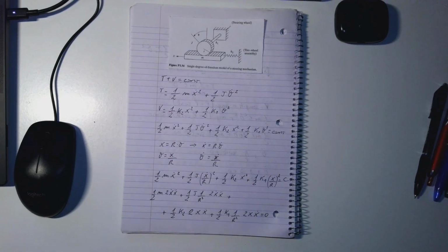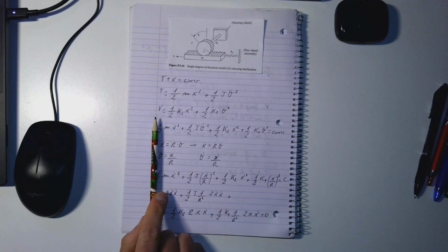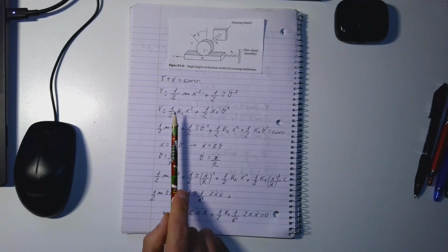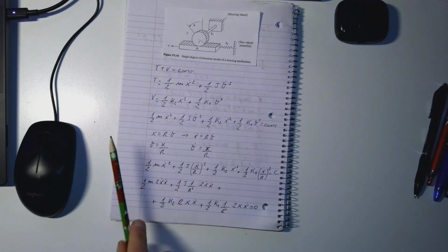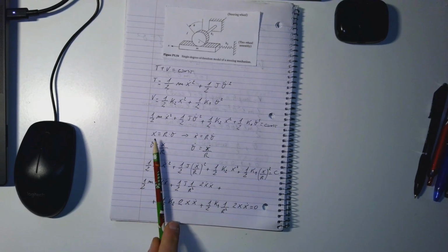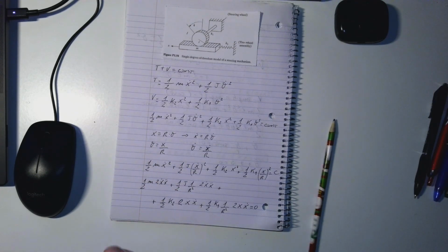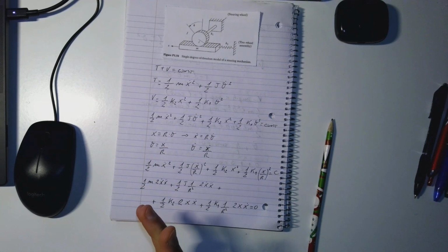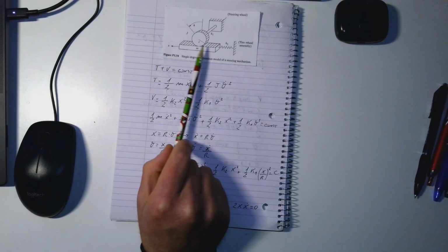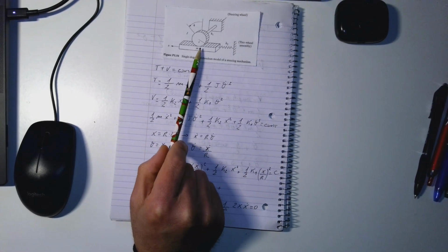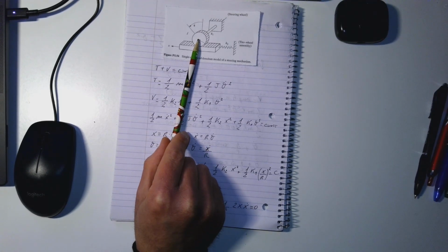So when we look at this, same thing, we look at the total kinetic energy and the total potential energy, and we plug these two quantities into our T plus V equal to constant. Of course in this case we have to be careful, because even if we have two types of motion, we still have 1 degree of freedom, because we assume that there is no slip condition between the mass and the disk.